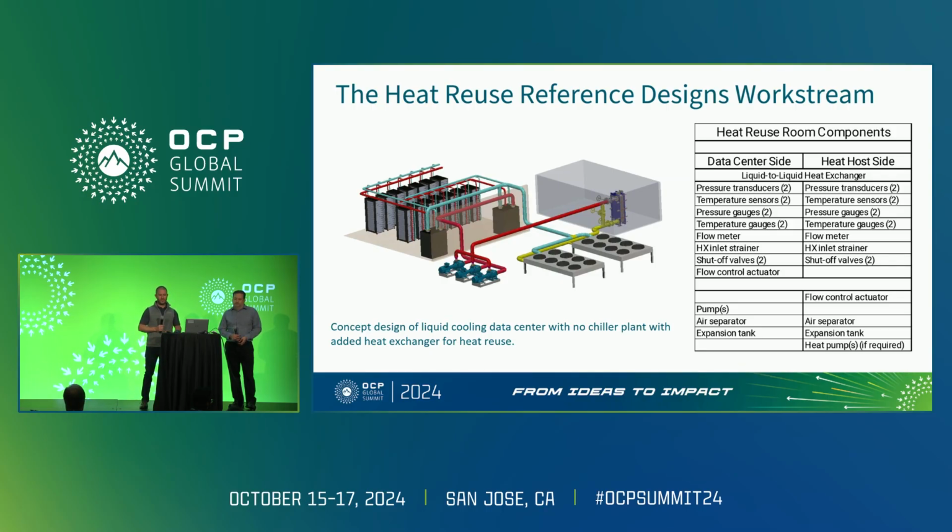In our white paper, we take a detailed look at the factors that influence how much space is required, but a general rule of thumb for a simple basic heat reuse system is between 3 and 6 square meters per megawatt of heat being reused. The majority of the space is for the liquid-to-liquid heat exchanger, which is critical for making heat reuse possible.